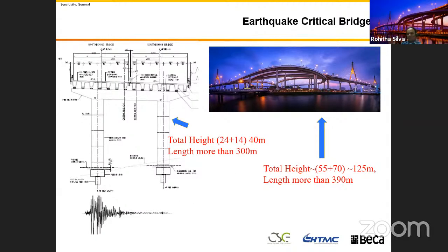At the extreme ends of the bridges, when you design for earthquake, it may sometimes not govern your design. By govern, I mean it may not induce forces as large as the traffic load.